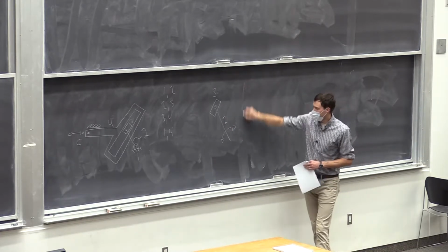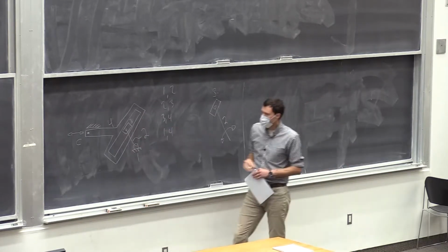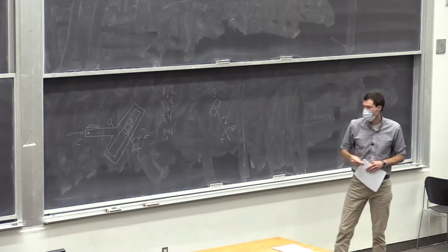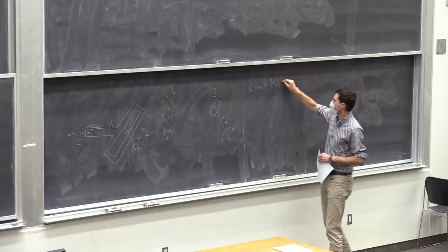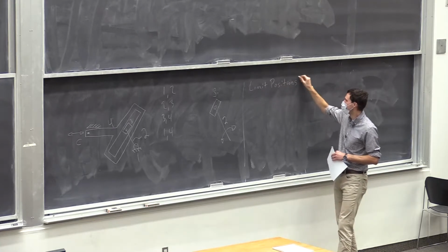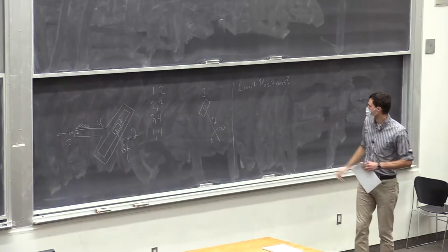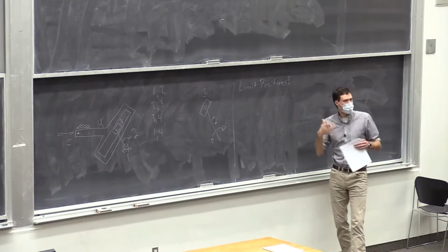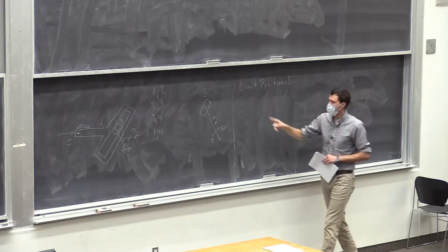The next thing after visualizing motion of these things is finding limit positions. That's a lot of what I'm asking you to do. Limit positions. And I hide some questions. In some questions are hidden things like limit positions, things like max or min velocity. Those have to do with limit positions. So that's my hint to you.